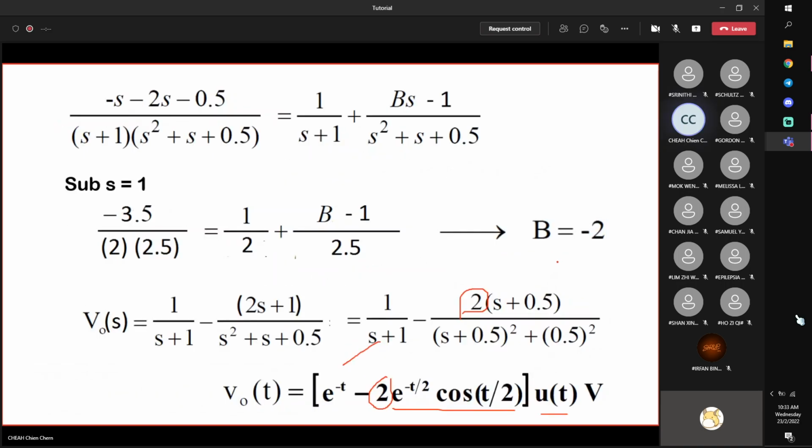Okay, so I hope everybody gets the idea. Given the circuits, put them into Laplace domain models for your energy storage elements, right? And then the relationship between voltage and current is similar to Ohm's law now. It's called impedance law. Then treat them as if they are resistors. Solve for it. In the end, you get some solutions in terms of s. Then you must take inverse Laplace transformations. If you can take it directly, go ahead. If not, express it as linear combinations of those signals that can be found in the table.